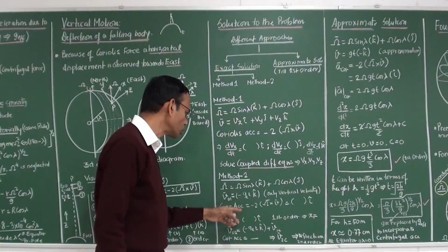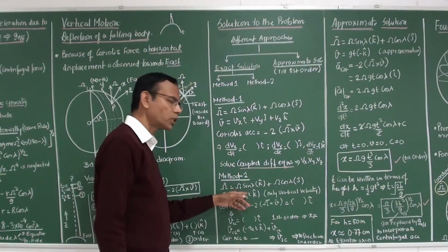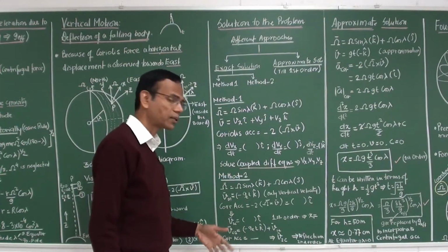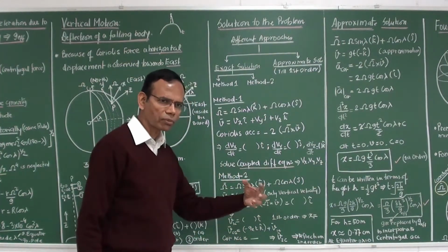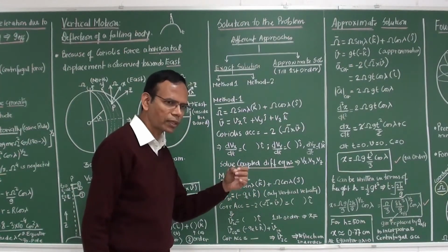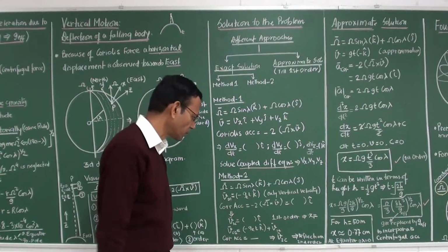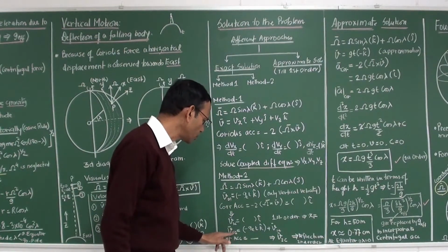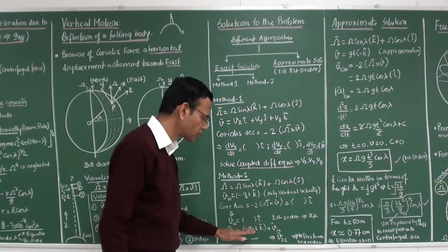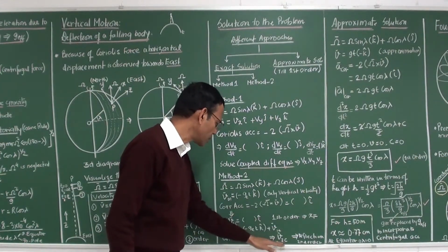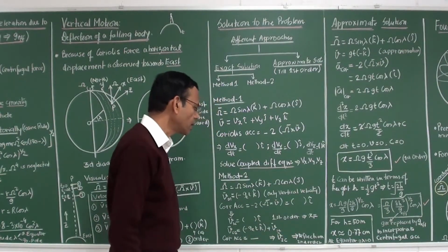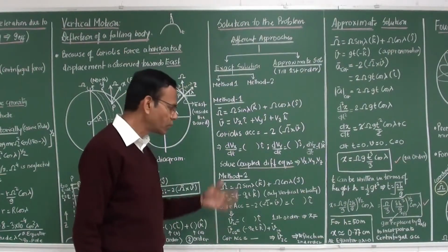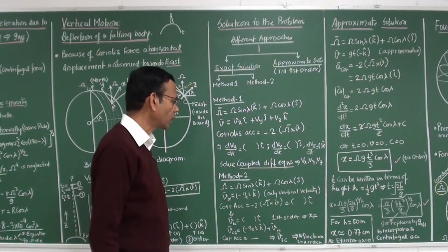Whatever velocity you get, you again put it back over here, again you do the calculation, again you put it back like that. The iterations go on, and finally you stop where the correction is very small, or the solutions match each other. So finally, you can calculate with v02 the corresponding acceleration, second order it is known as. From there you can calculate v2c, and from there the deflection in the second order. So this is another way of doing it. Maybe you can write a computer program and do that.